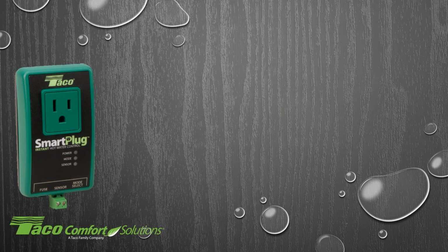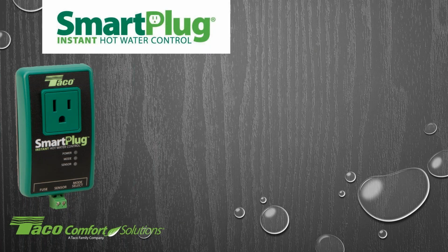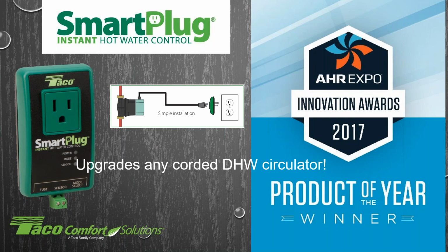Okay, so we look at the smart plug. It is a very basic device. It plugs into the wall. You plug the circulator into that. Off the bottom, there is a temperature sensor that we put on the hot water supply that's feeding out of the water heater, and it's going to learn when people use hot water in the house. So you could take any standard corded circulator and make it a smart circulator.